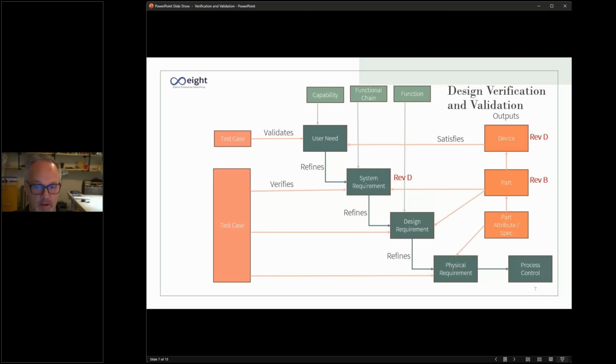And in the past, when I've done this, what I've done is really had 6 inches of paper, because what happens is you go out and you build the parts against a revision set, and when you build those parts against the revision set, they come back and we do an initial inspection and some initial testing, and on some level it fails. So we might have a dimension that's out of spec, and we're either going to change the print or we're going to change the process to make the part or change the design on some level.